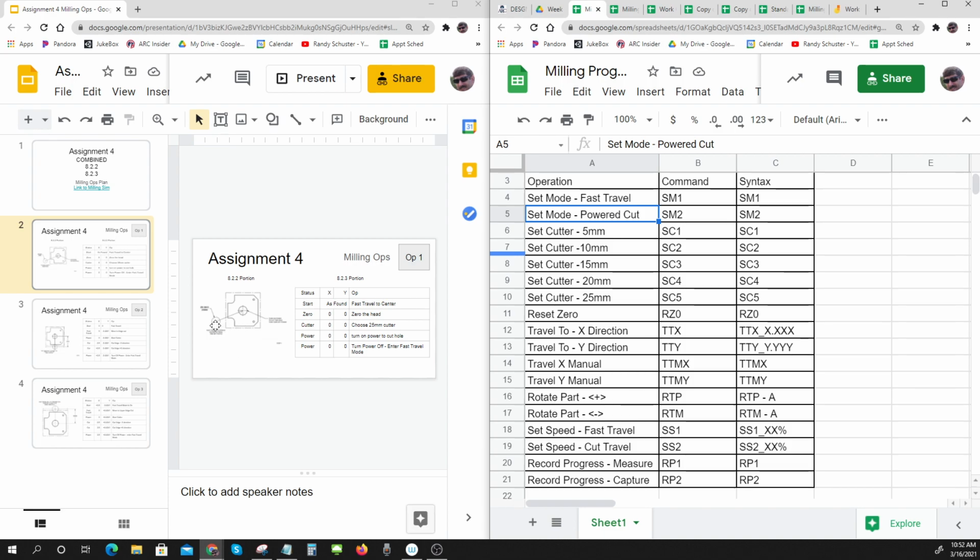If I want to set the cutter size, that's like doing a tool change. I have to tell it what cutter I'm going to use. Okay. When you did it, you went up there, click, click, clicked on the right one. Well, if you're going to tell a machine, you have to give it a command. And there are things called compilers that read this command and look in the machine and actually give the machine the bit by bit commands to travel to a certain spot, let go of one cutter, grab another cutter, go back to another spot.